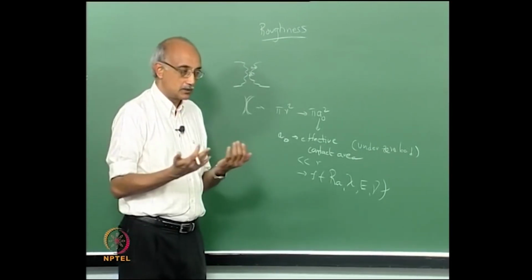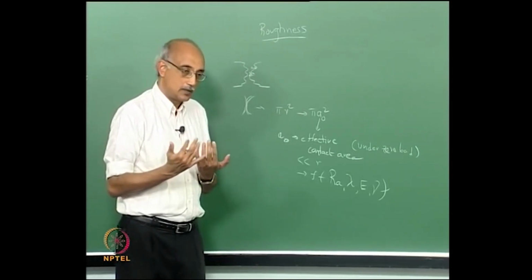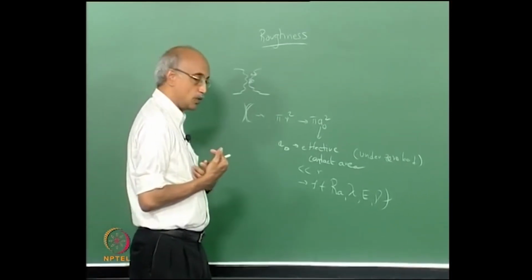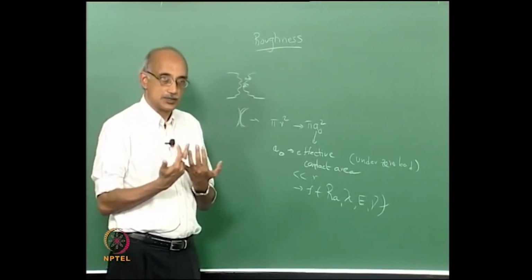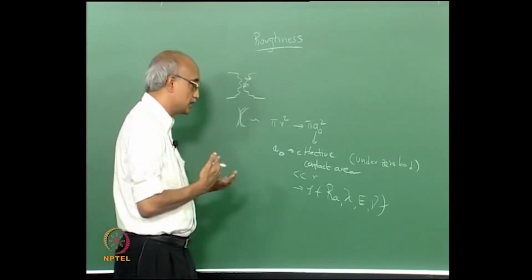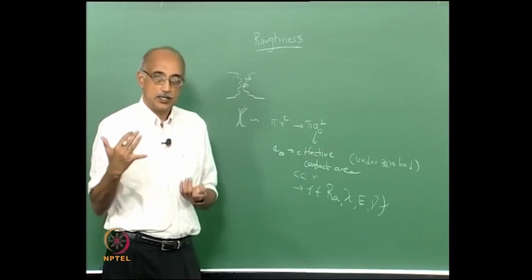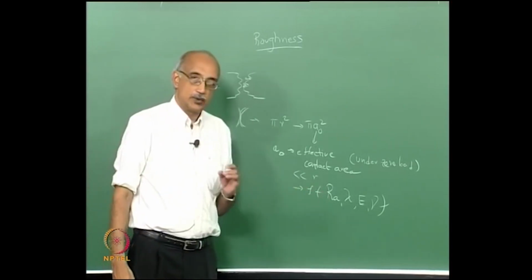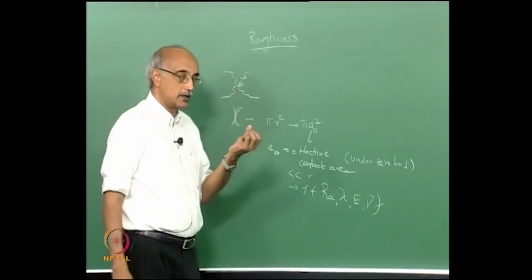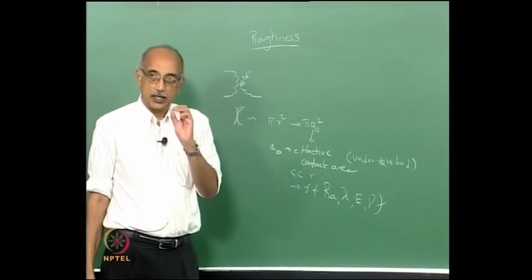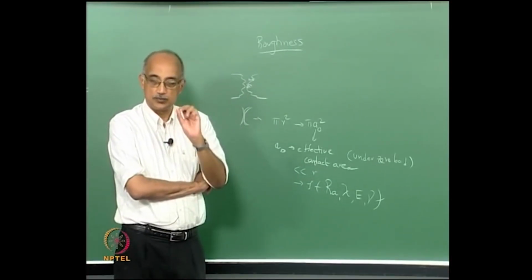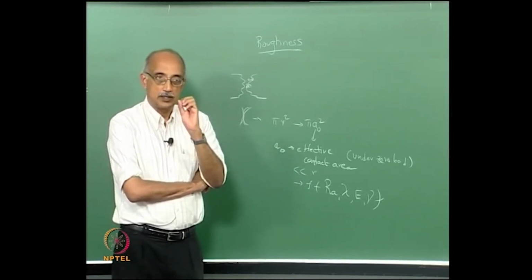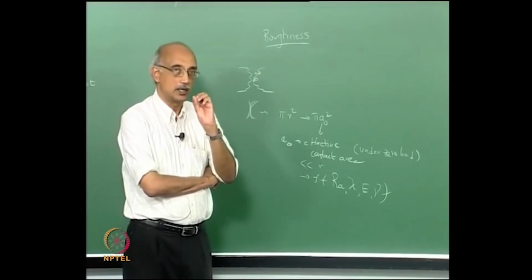In the plastic limit, the surfaces tend to deform a lot more, and there is much more accommodation of adjacent surfaces. So, in general, cohesiveness will be much greater in the plastic limit compared to the elastic limit. Another way of looking at it is, if you have two particles that are in elastic contact, the contact area is going to be very small compared to two surfaces that are in plastic contact, where the contact areas can be significantly high.